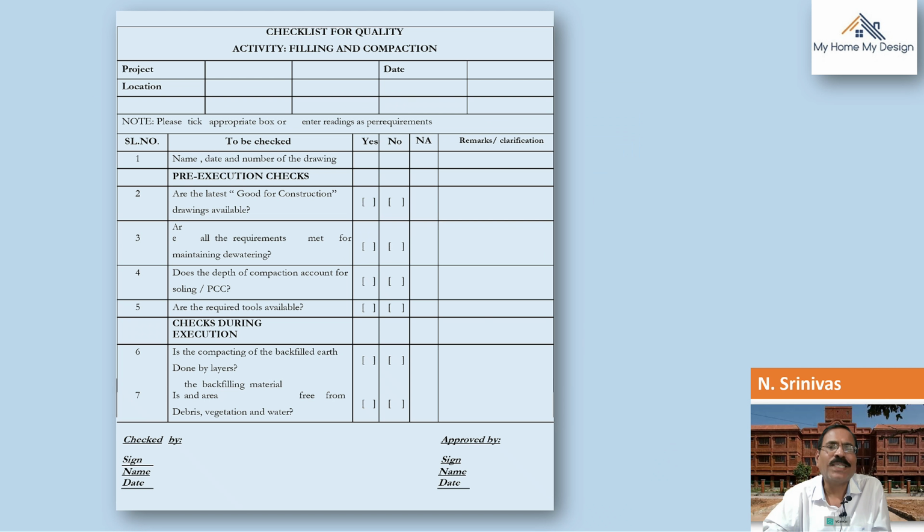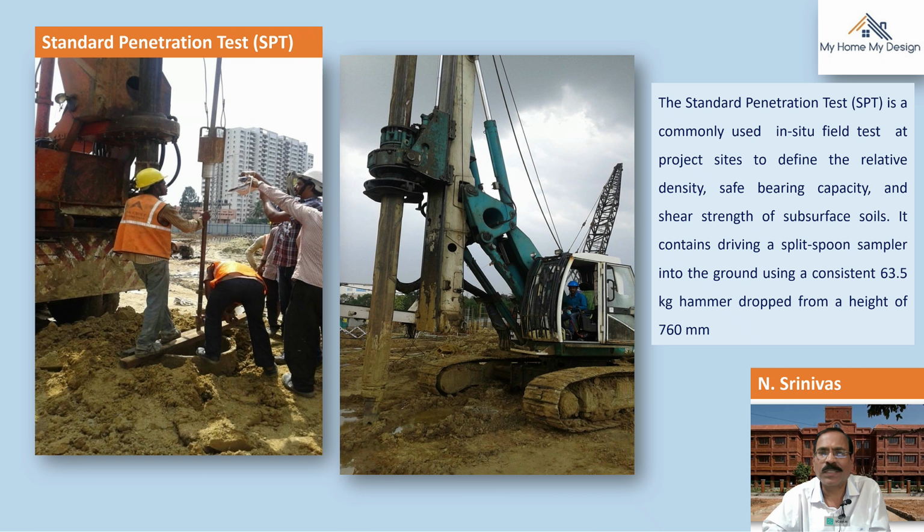And finally, the checklist: whether the pre-execution checks have been done, yes or no. Checks during execution, these are all the checks that have to be carried out. And the standard penetration test, after all these things. In some areas where a huge foundation is involved and the number of floors, let us say 15 to 20 floors or 25 floors, mega structures are coming, there we need to go for pile foundations.